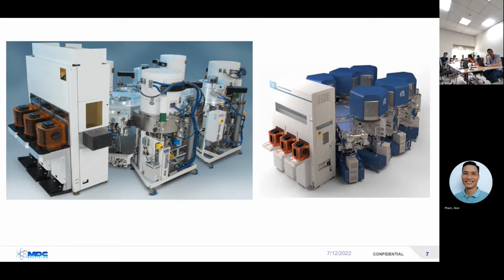Okay. It'll come out, but remember, that was just, in this case, a step to etch those holes, okay? Now it needs to go to the next step to clean off the mask. That's another machine like this. Then it'll go to another machine to make sure we clean off any particles. Then it goes to another machine set that does the next layer, okay? Then after it gets the masking on it, those wafers come back, now they're at layer 2, and they come right back to this machine and start to do the same thing. Okay, so over 100 times.